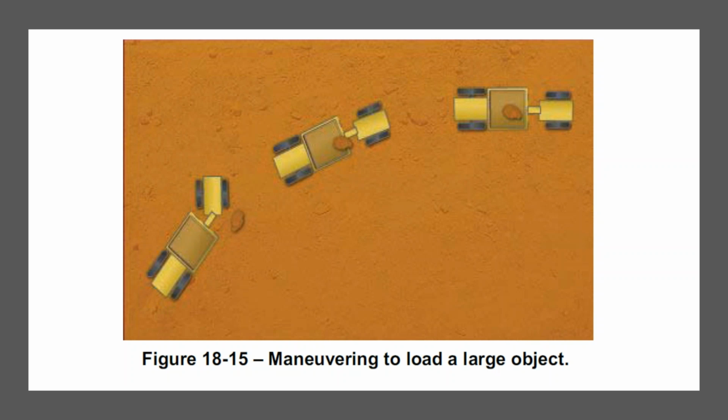Scrapers can do other jobs as well. One of the jobs you encounter in glacial soils is erratics, big boulders that have fallen out of the glacier. Those can be picked up by maneuvering, and anything of substantial size can be, as long as you can engage the cab around it, you can pick up a piece of soil. So you frequently see this because people like boulders on their property for some unknown reason. Often boulders are collected in one location and they're sold for a great deal of money. So in those particular cases, you want to be able to pick them up and move them without damaging them. Any other method of moving them will scrape them a great deal, but scrapers can lift them with very little damage.